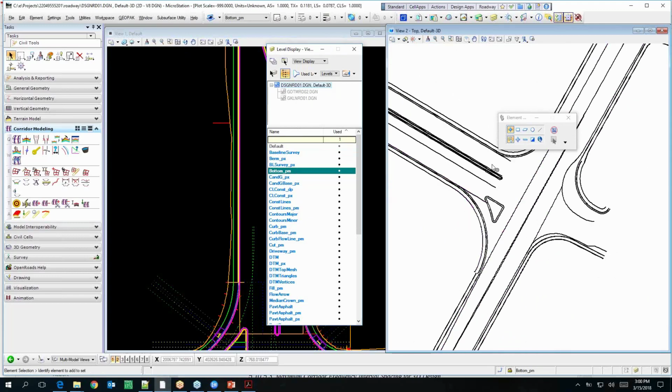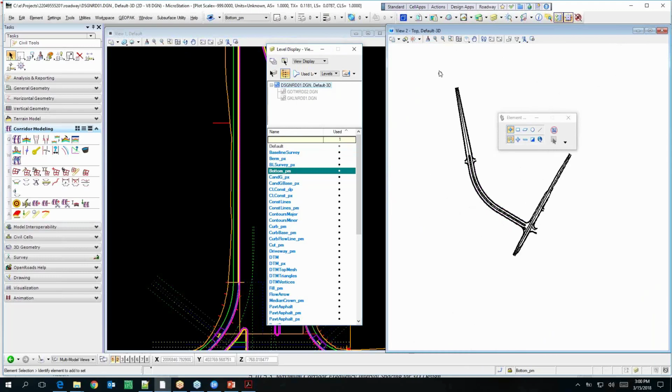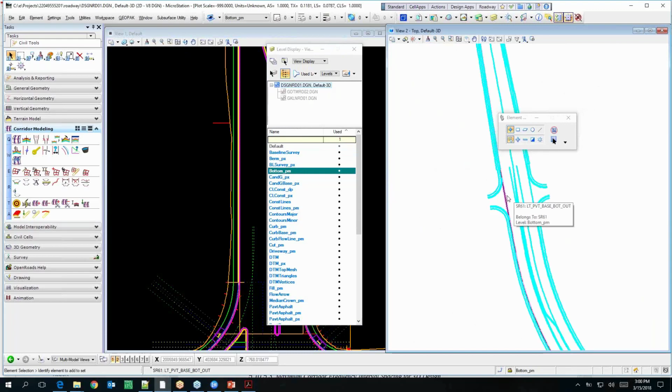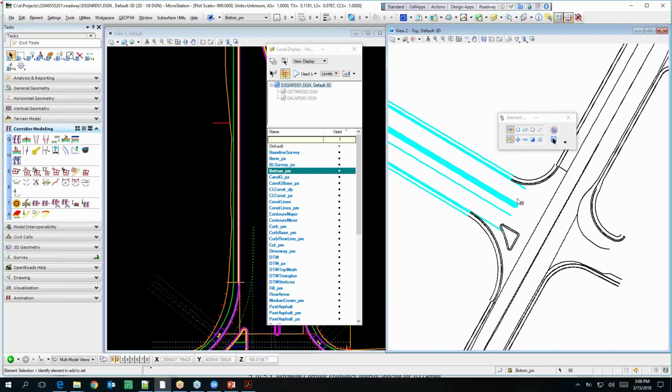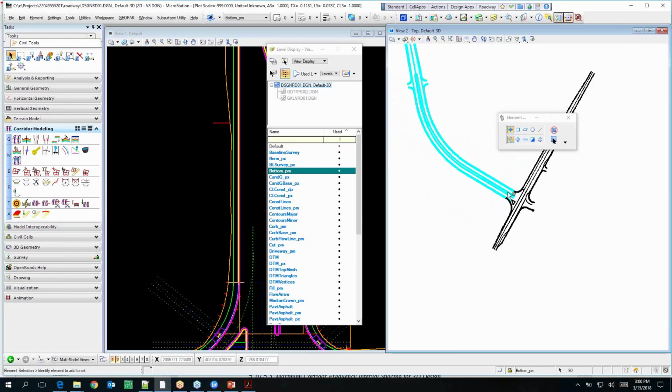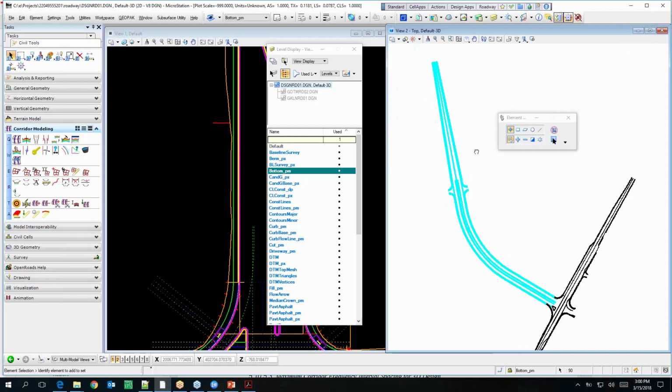So there's going to be some overlap in the linear templates and then 98. So really the only thing that's going to look right is this section. So I'm just going to select the lines that are part of this corridor, since I know the others don't look right. Okay, looks like that's it. And then we're going to export that into a 3D terrain. Go to terrain, create from elements. I could do that in this file, okay?